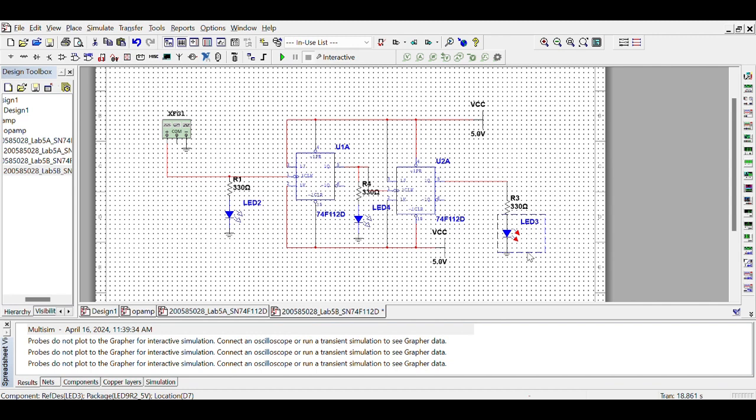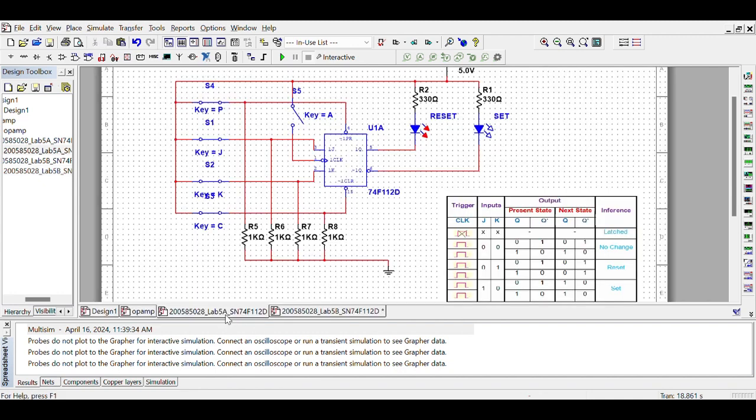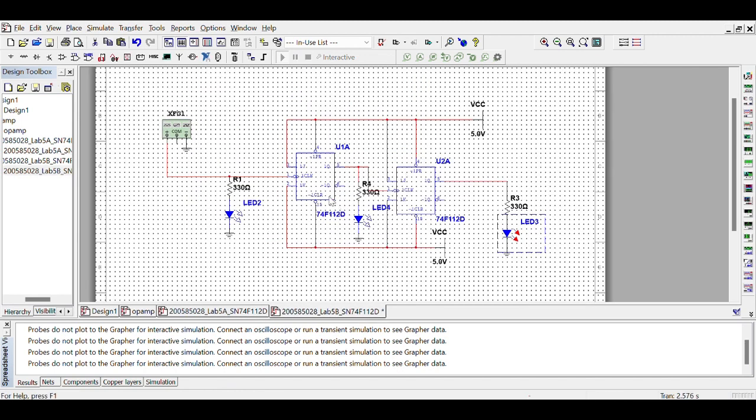And so if we return to this one, we can see how when we swap A, you get this one high, on the next stage, this one is high. Since we've only got the LEDs connected to Q, it makes this set basically disappear. So you've only got that reset showing up. So basically every other time it will illuminate. And again, that's why we lower the speed by a half.